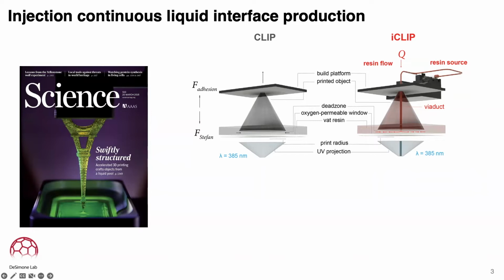While accelerating printing orders of magnitude, the CLIP process traditionally still suffers from severe mass transport limitations associated with flow through this thin, typically tens of microns, dead zone gap. Ultimately, this causes print failures and slows down the process, which should be able to go more quickly.